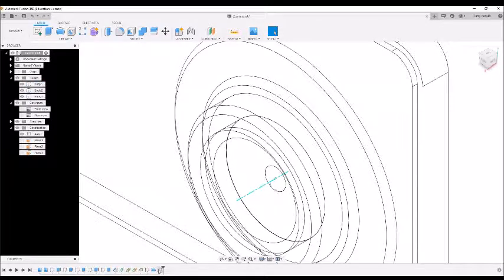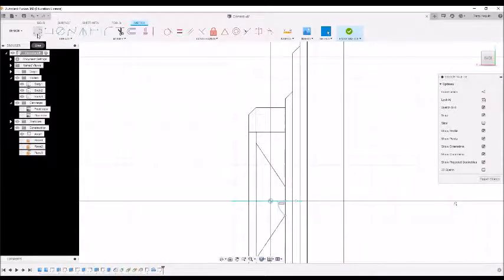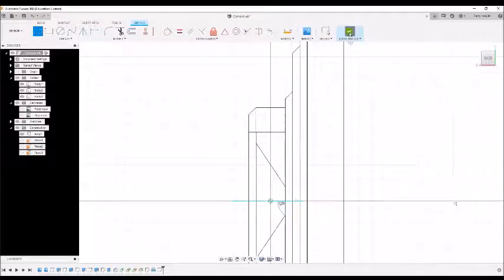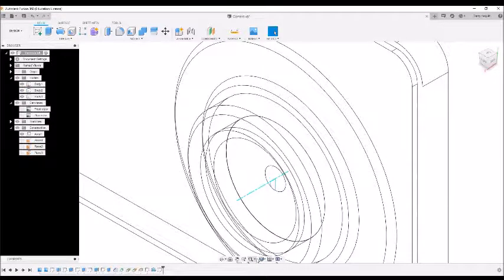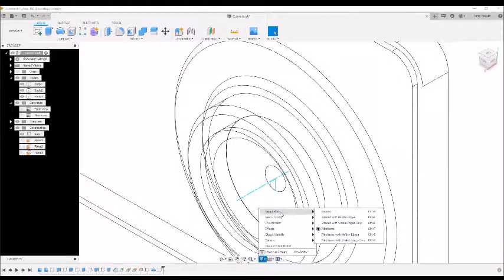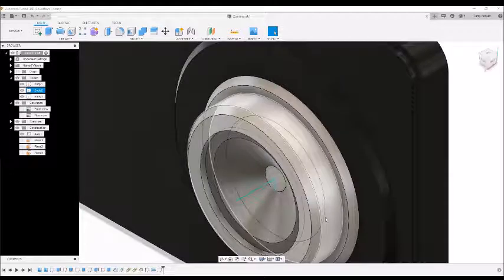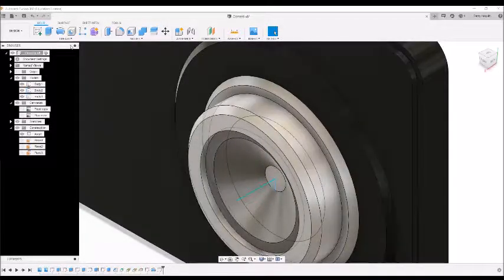So what I'm going to do is click down on the sketch at the bottom of the screen and right click on it. I'm going to go to edit the sketch profile, and then I can put a line in from the base of the arc to the top. So if you do go wrong with the sketch, you can go back into it and edit it. Now all I need to do is change it back to a solid view so I can see what's happening. And I'm going to use the revolve tool one more time to revolve this into a solid lens shape.